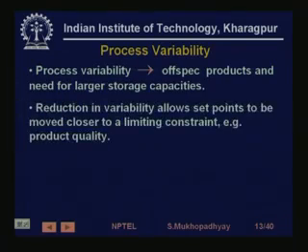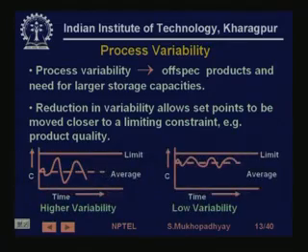The second thing which is important for production is process variability. Typically you want to maintain a certain set point you are holding, but still the process signals or the final product parameters vary, let us say a steel strip thickness coming out of a rolling mill, where you have the same roll gap.